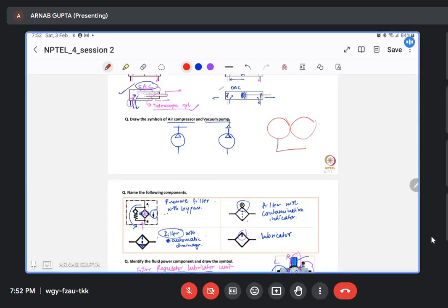See, flow dividers can be of different types. There are standard proportions. You do have 50%, 55, like a 1:1 flow divider, where suppose the discharge Q is going in from here, Q/2 goes out from both sides. So if you have two hydraulic presses, one running at Q/2 and the other also running at Q/2, then you use this type of flow divider. Okay.